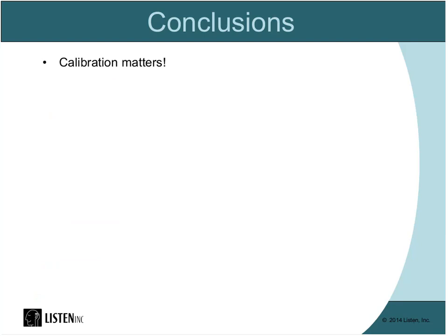If you don't calibrate, you're not going to get absolute measurements, and you might not even know what you're getting. Use a reference resistor. Make sure it makes sense. Good cables and connections matter, and again, all the more reason to use a reference resistor. If for some reason you have good cables and good connections and you measure a 4-ohm resistor that's not 4 ohms, then you have to ask yourself, is it my calibration or is it my cables or both?